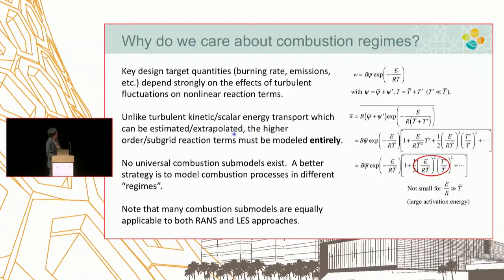I'm talking about the example of large eddy simulation, where small-scale, we call it filtered, subgrid-level information is approximated based on the knowledge of the large scale. I will elaborate on that more later, but the whole notion is built around the concept that it can be extrapolated because we know the turbulence spectrum.